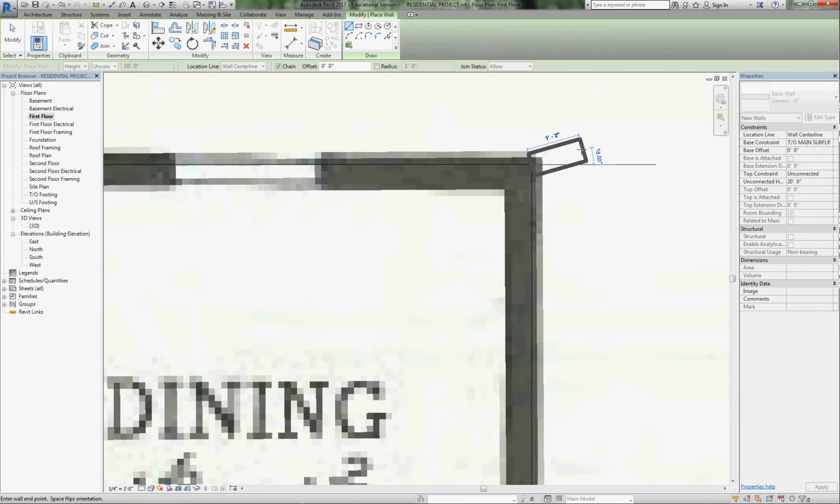Core is the structure face. That's what we want, and in our case that would be face of sheathing, and we will create more detailed walls later. The importance of this is when we switch this generic wall for a more complex wall, our core boundaries are going to be what stays in line, and that's really important because otherwise our dimensions would change.